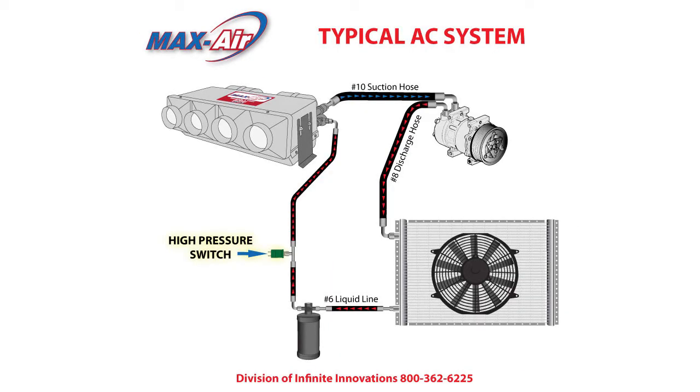The AC pressure switch is a safety switch installed into the high side line of the air conditioning system. When the pressure rises too high, the switch will turn off the compressor to prevent damage from occurring. Also available are low-pressure, binary, and trinary switches for automotive AC applications. A binary switch protects the system when there is too much pressure or too low pressure. A trinary switch does the same as a binary switch, but includes a switch with an additional fan engagement signal.